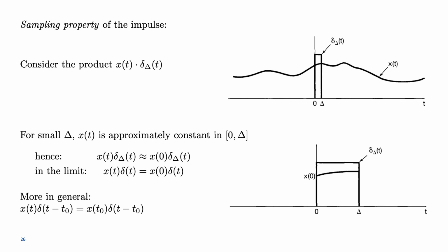So the unit impulse that we have introduced should be seen as an idealization, right? While an ideal impulse does not exist in nature, you can think that all systems have a certain inertia, right? So systems take some time to respond to an input. Therefore, if you have a pulse that is sufficiently short, then the system's response to this pulse is actually not affected by the duration of the pulse. It's just affected by its energy, by the area. Okay? So the unit pulse could be regarded as a pulse that is short enough for any system under consideration.